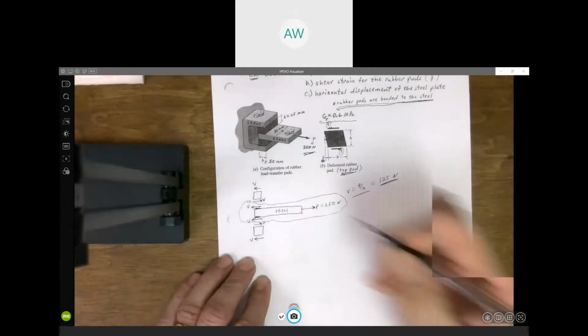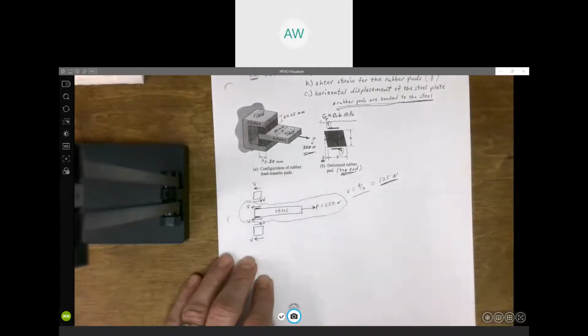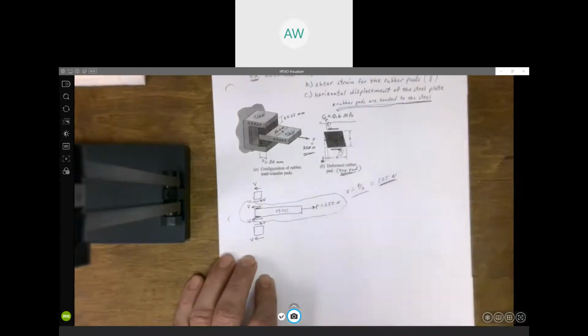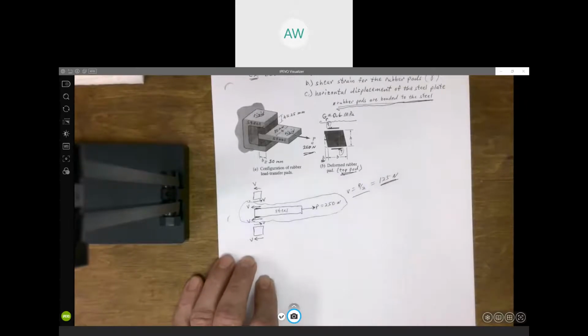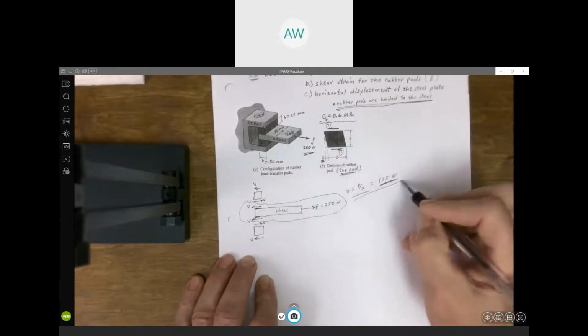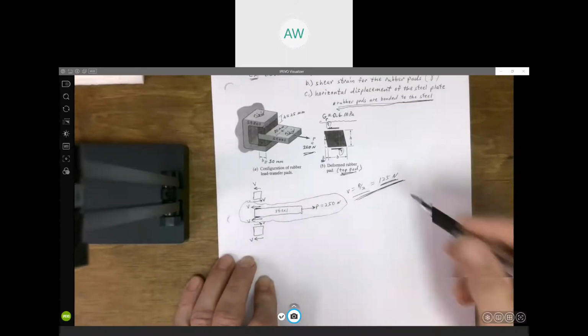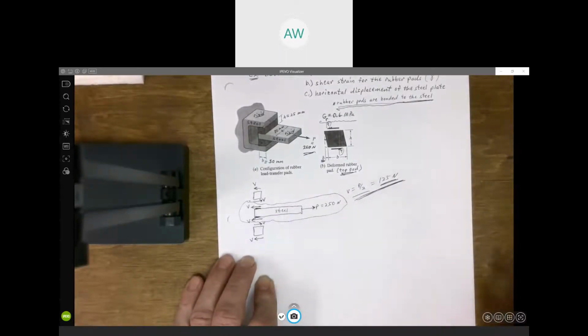So this shear force V has got to be 125 newtons. It's acting similar to what we talked about with single shear and double shear; this is basically behaving like a double shear joint. But does this make sense? Everybody with me? That's how I know the shear force V is 125 newtons.